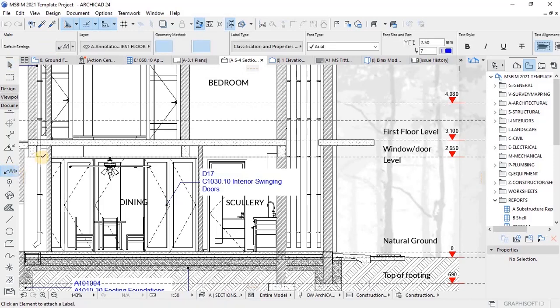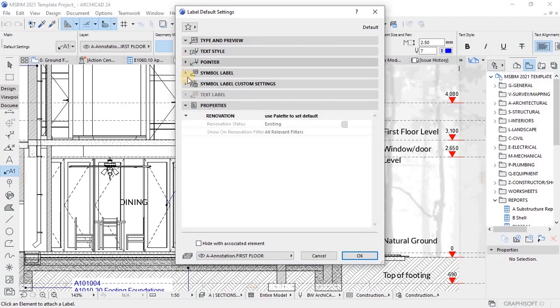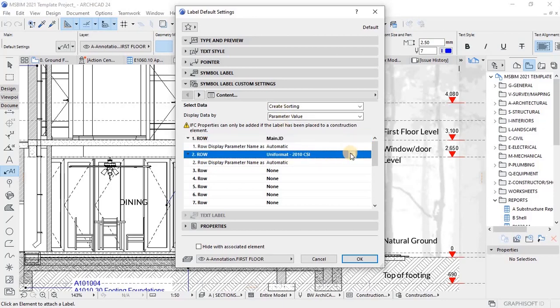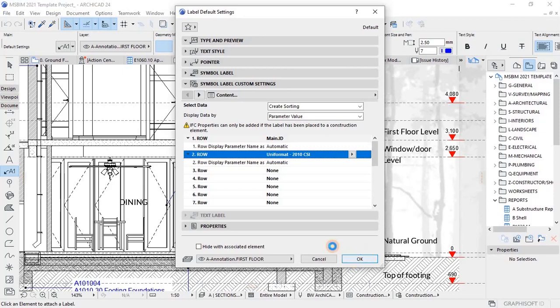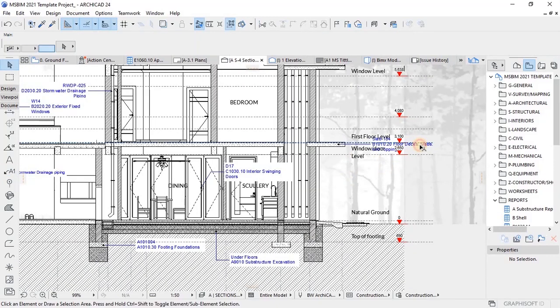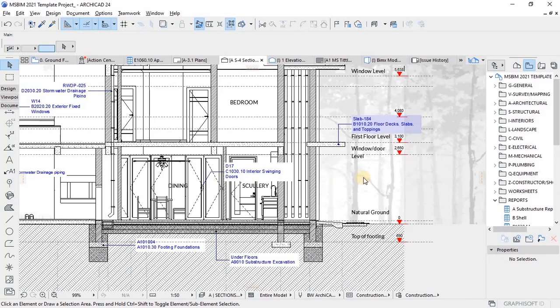Once you're doing your drawings, you're going to have to label your building elements, your components, and you need to use a classification properties label, and then you set your sort criteria so that you could extract. Using Uniformat, the classification you want to label using, and the properties managers, you just label now. Just pick anything you want to label, drop a label. You can label any element. It's automated. Your walls, just click. Your window, you just click. Your furniture, you just click.